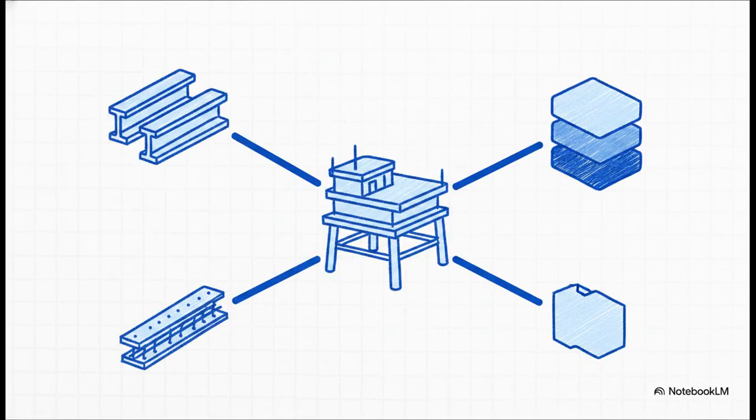Because the steel structure doesn't move and certainly doesn't require a marine buoyancy certification, the feeder data is so much more straightforward. Your primary feeder data consists of structural steel drawings, topside jacket fixed supports, and rigid cable tray routing plans. It is rigidly tied to standard structural and electrical engineering plans mapped to your standard Zone 0, 1, and 2 areas. And it's all governed by general IEC or API standards, completely without that heavy Marine Classification Society overlay.